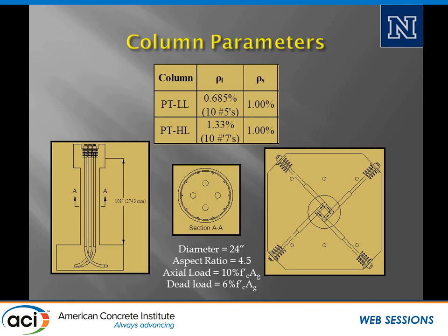Another project that we did, this one was funded by the Nevada Department of Transportation. In this one we took that idea of the post-tensioning, but we started to look at actually having reinforcement cross the joint. So in that we looked at two different longitudinal reinforcement ratios. Again, this is post-tensioning in combination with conventional reinforcement. We kept the transverse reinforcement about the same at 1%.